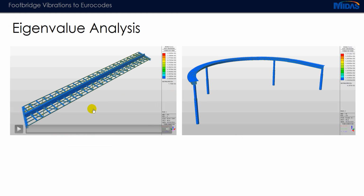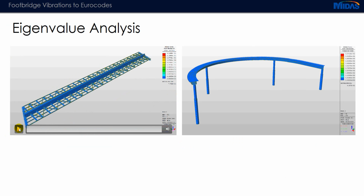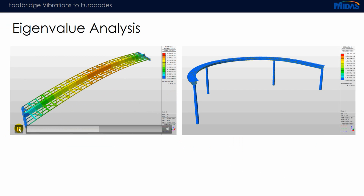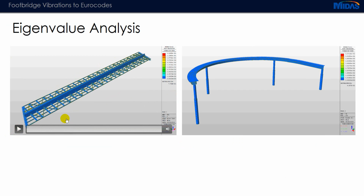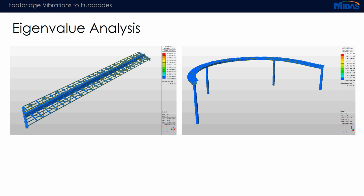Okay, so free vibration analysis or eigenvalue analysis, as mentioned before, depends on the stiffness and mass of the structure. So there may be different modes of vibration. We have to identify the correct vibration mode which applies for the particular check, lateral or torsional or maybe vertical vibration.